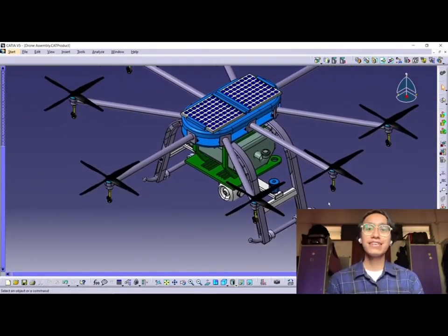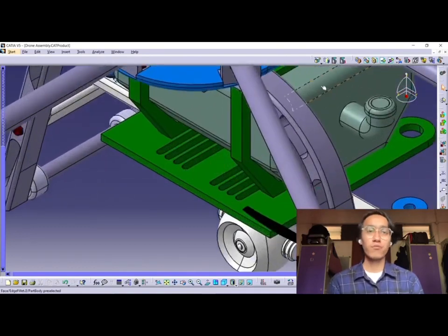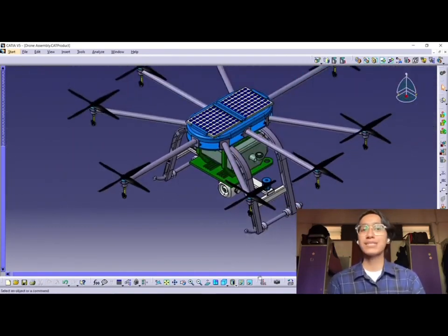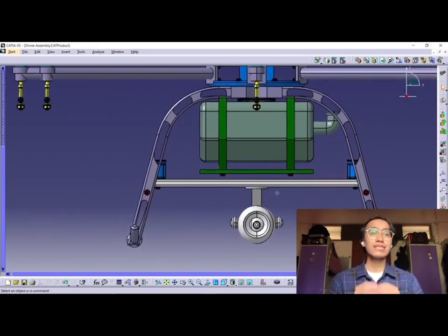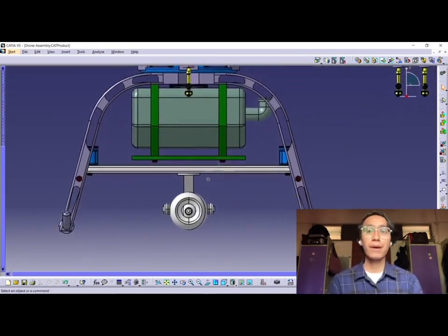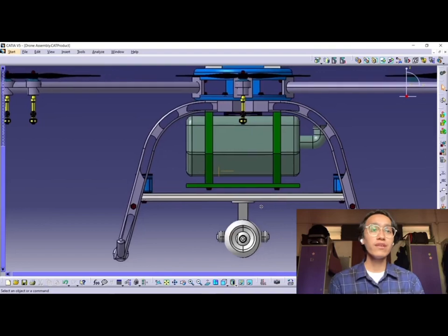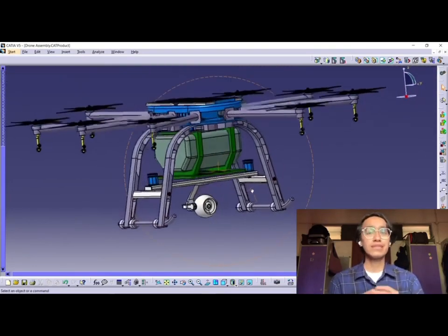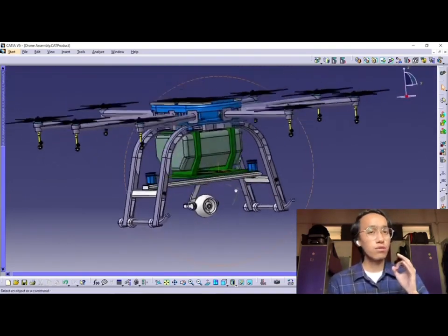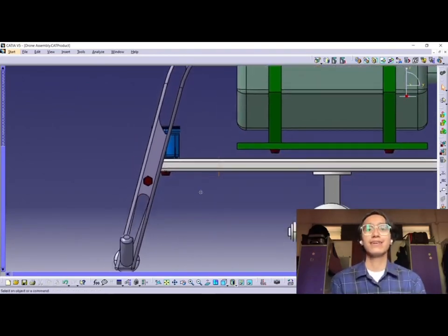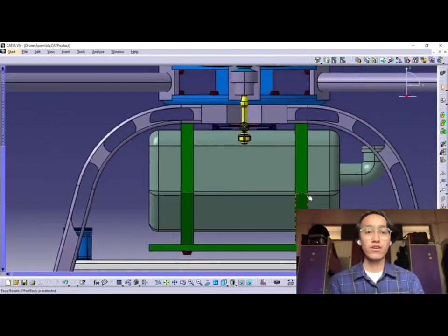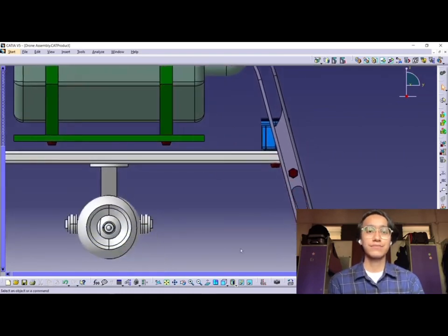Thirdly, the landing gear is not able to support the structure properly due to the heavy weight since the pesticide tank has been added. For this part, the shape of the landing gear will be semicircle to absorb the impact when landing the drone. It will prevent the landing gear from breaking during the landing process. There will be several holes designed in the landing gear so that the air can flow through it. It will reduce the drag force and the air resistance.